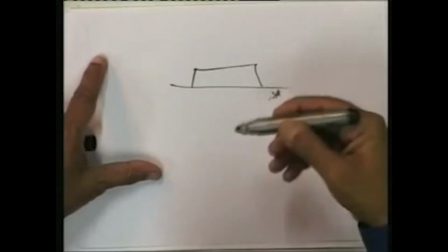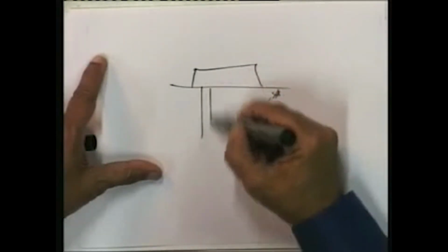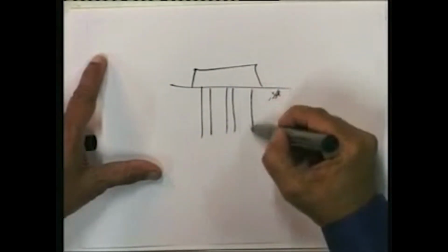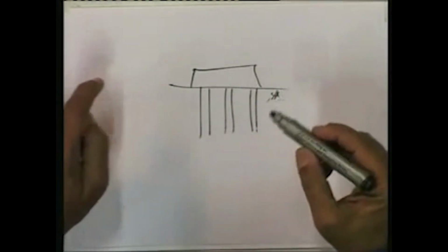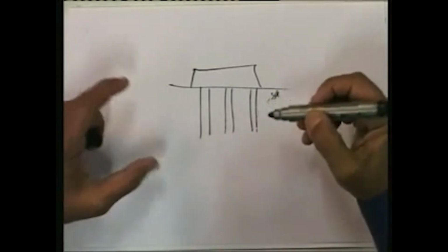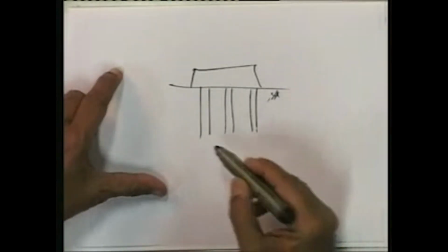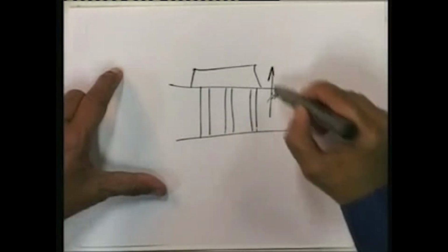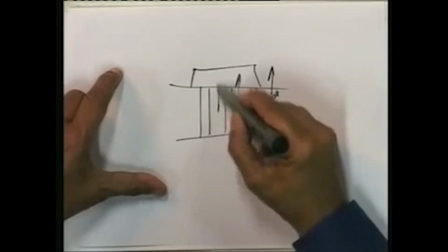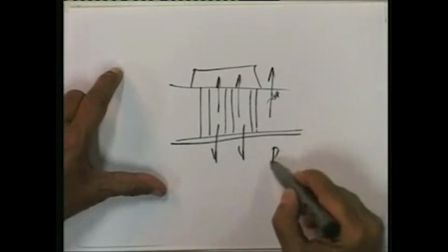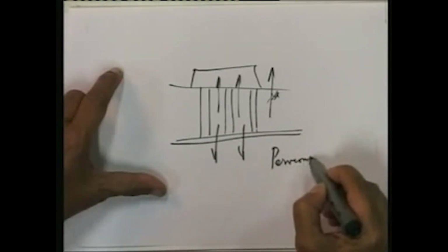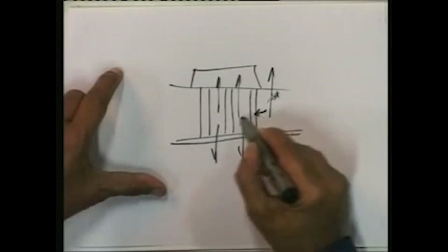In order to facilitate this consolidation, if you install what are known as sand drains, we had discussed this also in the past lecture, then the flow of water takes place due to excess hydrostatic pressure not only in the upward and the downward direction if the downward layer is also pervious, but it also takes place radially.